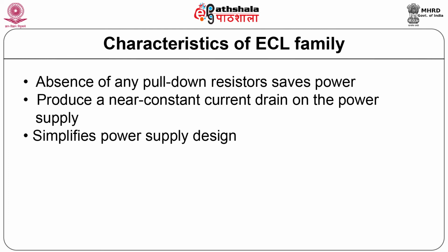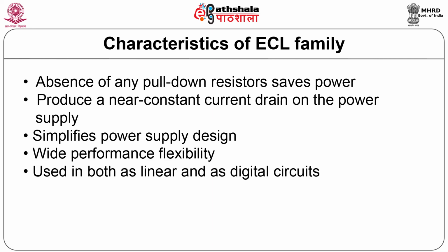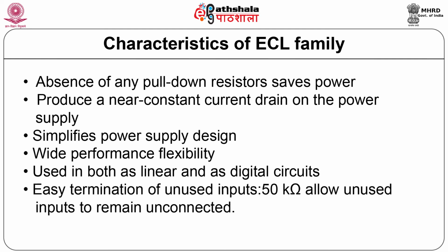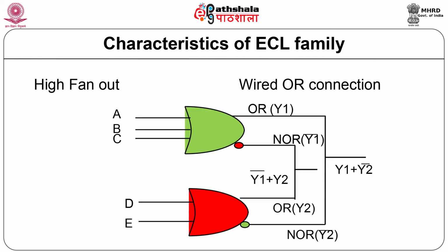On account of the differential amplifier design, ECL devices offer a wide performance flexibility, which allows ECL circuits to be used both as linear and as digital circuits. Termination of unused inputs is easy. Resistors of approximately 5 kilo ohm allow unused inputs to remain unconnected. High fan out or wired OR connection is the characteristic feature of ECL family as shown in the figure.